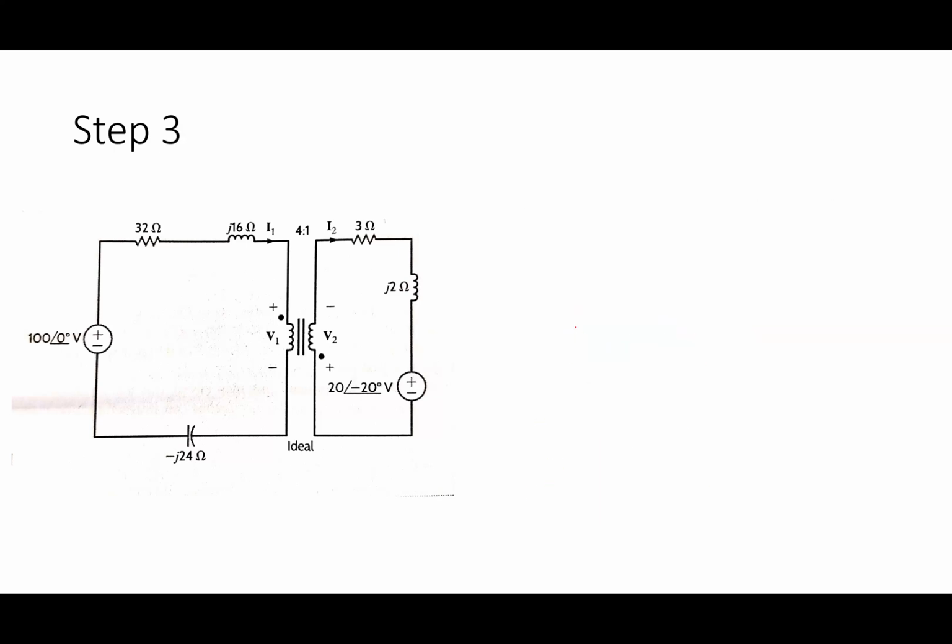So I basically have V2 equals V1 over 4, like that. I also have V1 I1 plus V2 I2 equals 0. One of the things people like when we get into power and transformers and all that stuff is we usually don't have weird loops with dependent sources going this way and that way. Usually they get much simpler. It's usually 2 loops, and they're usually simpler circuits. And this is a relatively simple circuit. There's just 2 meshes to deal with.